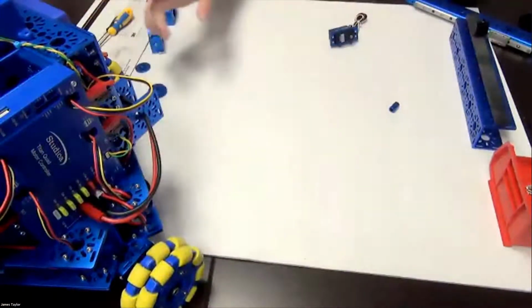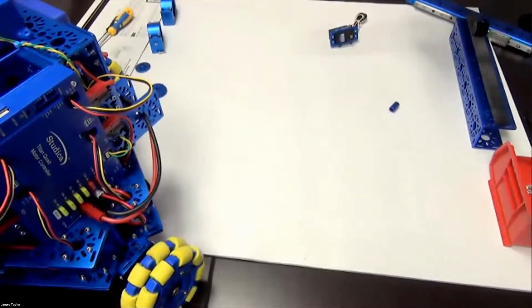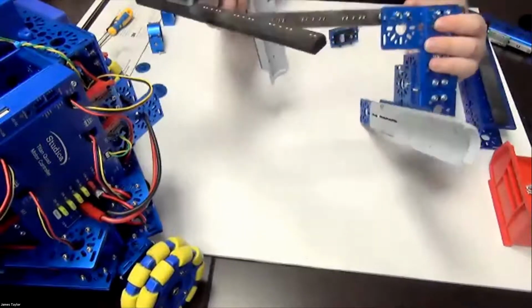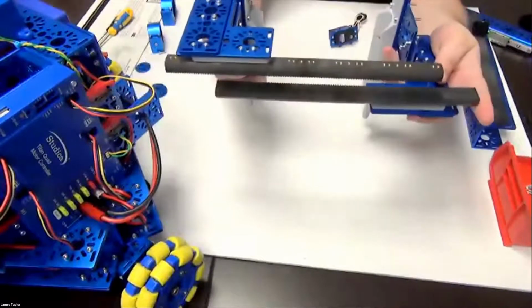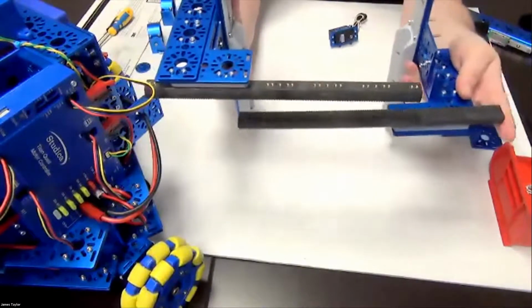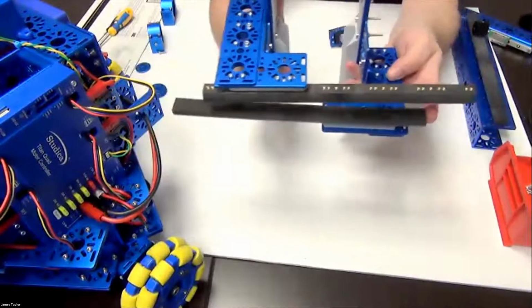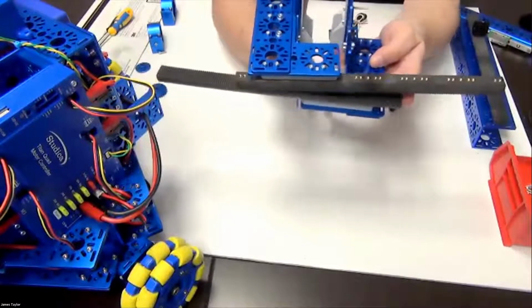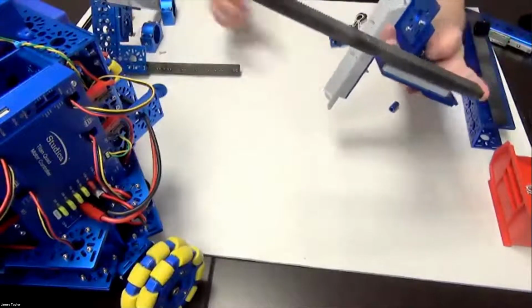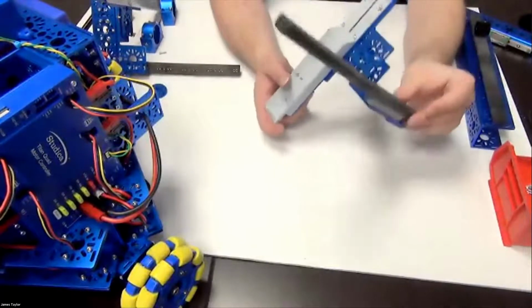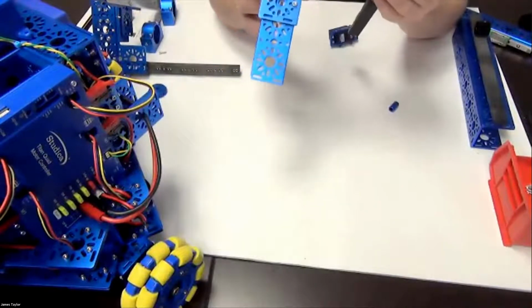So before we attach to the robot, there are two arms that are used to clamp the ball. They will act as a differential. So essentially we'll use a pinion gear attached to a servo that when rotated will bring them in, and when rotated the other way, will push them apart. Each one of these arms has one rack and pinion on it, along with some channels and brackets.